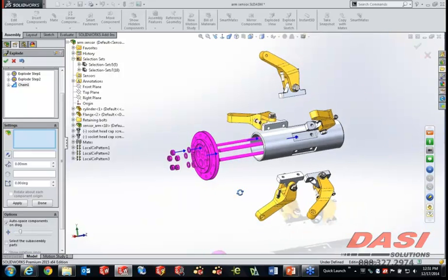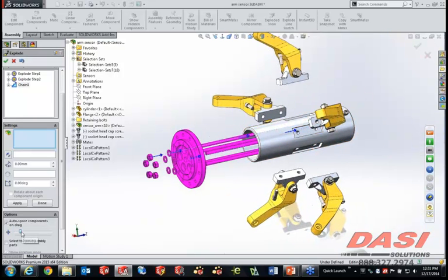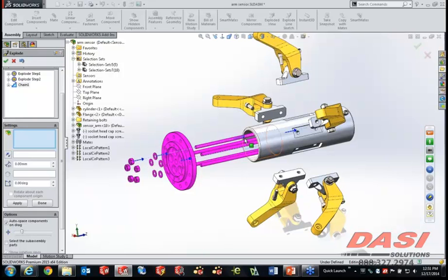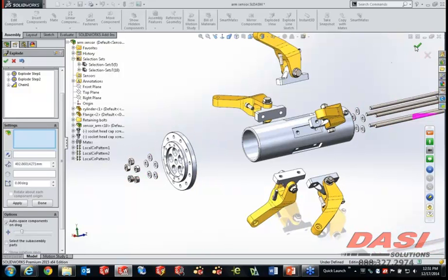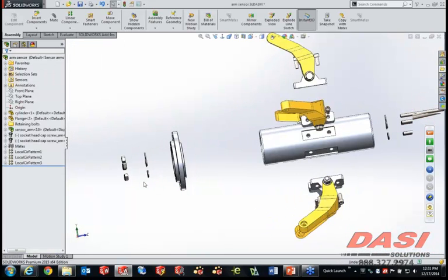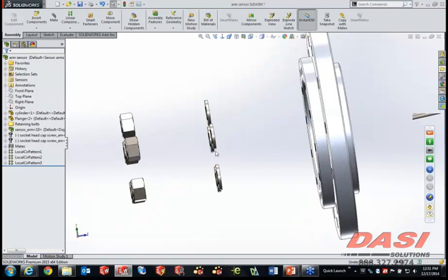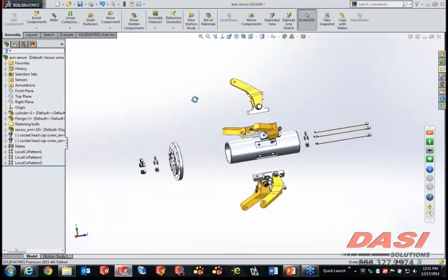Now one thing you might not have known about this tool is that we're in the middle of autospace here. We can change the spacing in the middle of this. We can also sort things, take them into a different orientation, maybe drag them in a different direction, put them opposite of each other, and simply reposition these to any little minutia distance changes that we might want to do. But it groups them nice. They're all in the same coplanar faces, and they wouldn't come out to 5 or in fact 10 different distances because they happen to be 10 separate components.